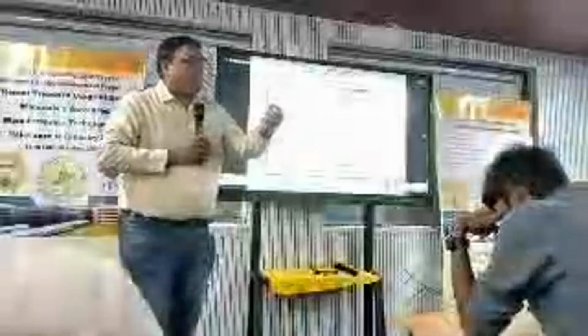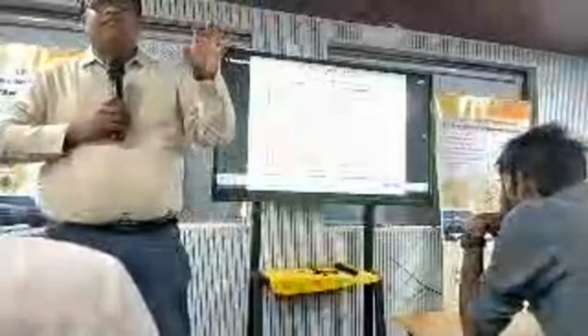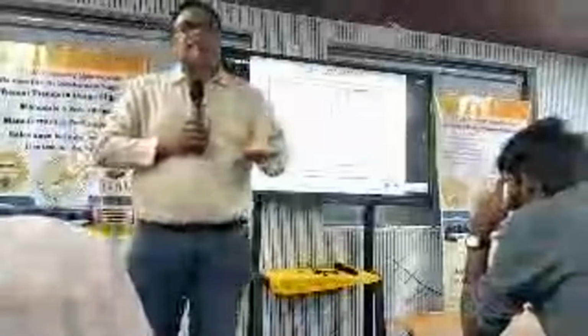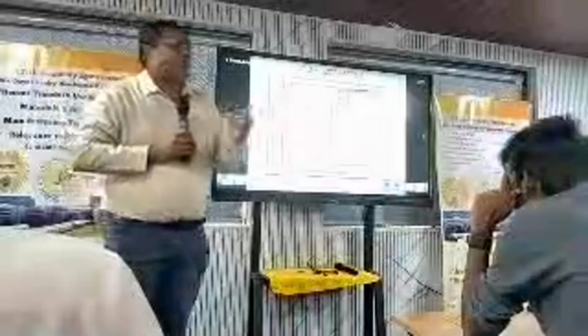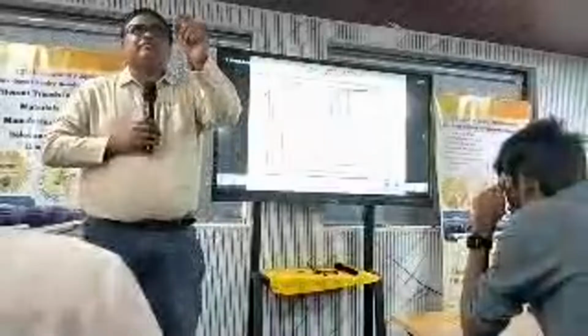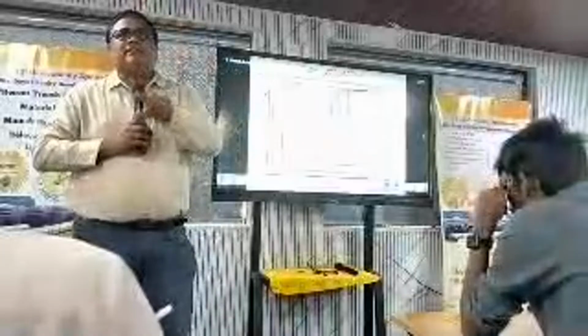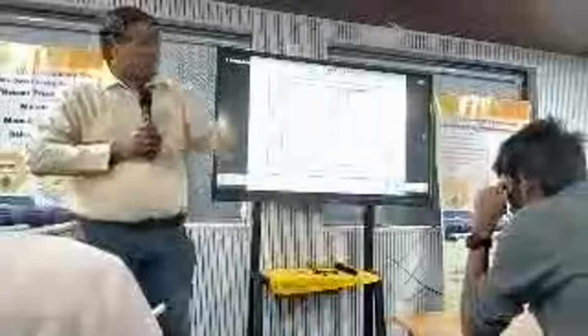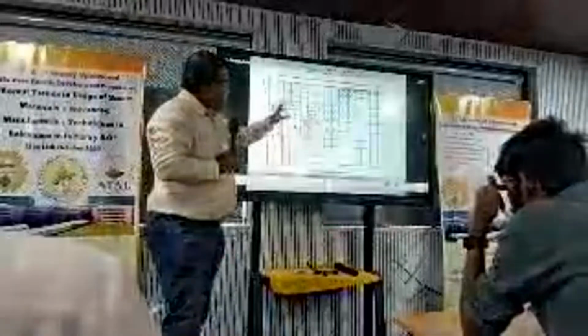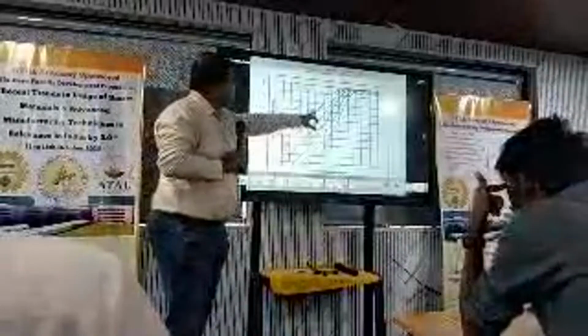If you design, we have the steel material, whose Young's modulus we know. With the viscoelastic material, we have to design the combination such that the modulus ratio is 0.1. Let us assume steel's modulus is 10, and the viscoelastic material's E2 is 1. Then 1 by 10 is 0.1. Like that, we have to design the viscoelastic material's modulus, so that the ratio is equal to 0.1.